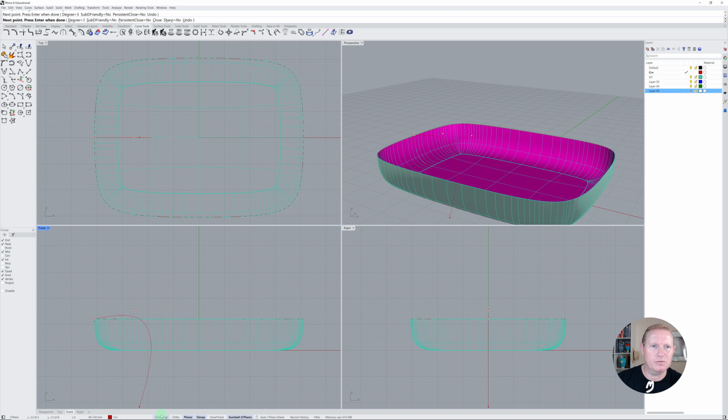I better make sure I've got my grid snapping turned on, held down shift and snapped into the middle. I grabbed those 2 and I brought it down. I'll probably grab that one and I'll shift it around a bit. I got that curve and I mirrored it around the end point and held down shift.